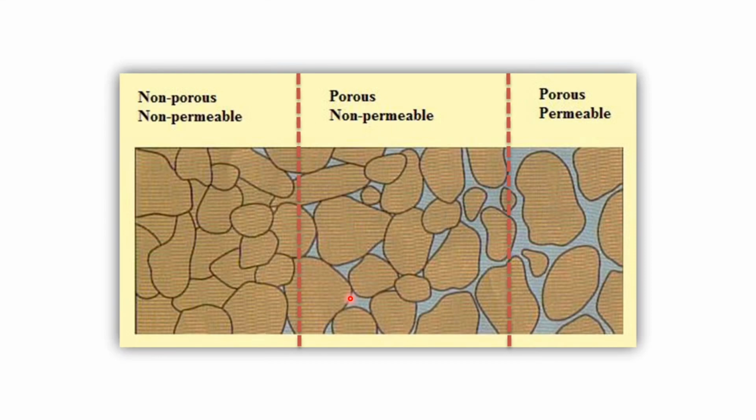Permeability, we know, is an important lithological parameter, and we have two types. Intrinsic permeability is a measure of the ability of a porous medium to transmit a liquid under a potential gradient. The hydraulic conductivity is the quantity of water that will flow through a unit cross section of area per unit time at a specified temperature under a hydraulic gradient.